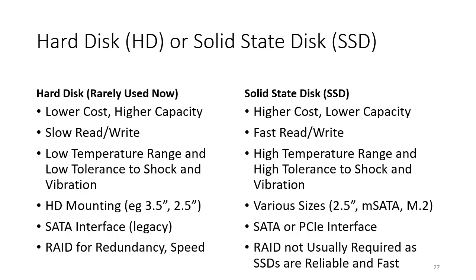For industrial PC and mobile applications, they have a high temperature range. You can buy SSDs which can go down to -40 and up to +85 degrees. So they're very good for industrial and automotive type applications. Because there are no mechanical components, they have a very high tolerance to shock and vibration, so they're ideal for industrial and mobile type applications.